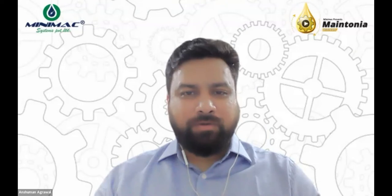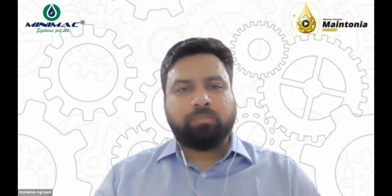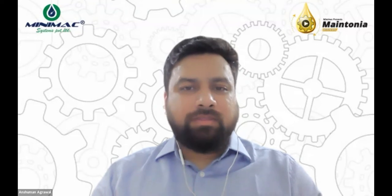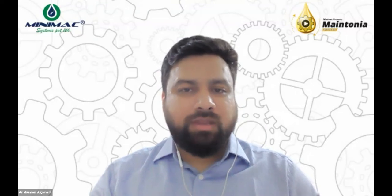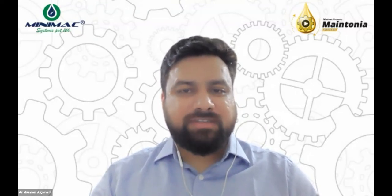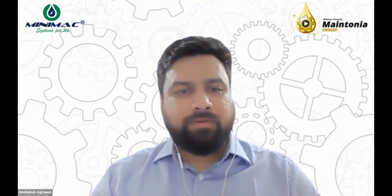Replacement is out of the question. Certainly don't think about it. And all the oils, unless and until they are super highly degraded because of malpractices, we don't need to replace the fluids first of all. The reason why the moisture would still be present in your fluid, even after the usage of centrifugal, not pump, but centrifugal purification or separation systems, I would say. So these centrifugal systems can remove only free water content from the fluid.